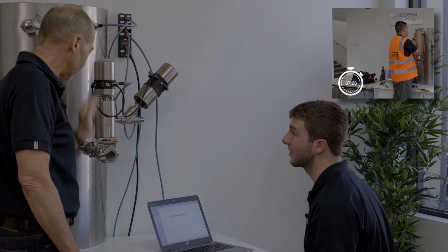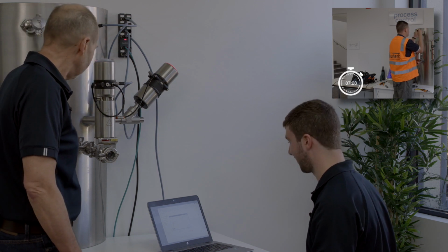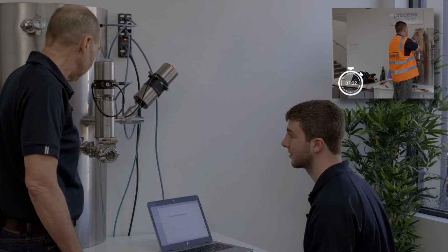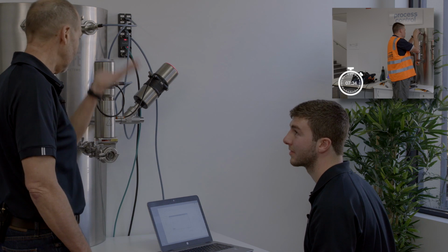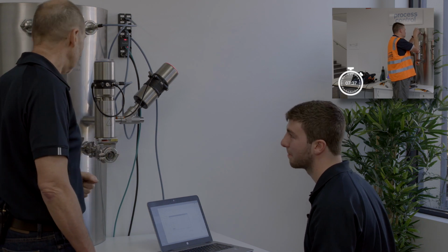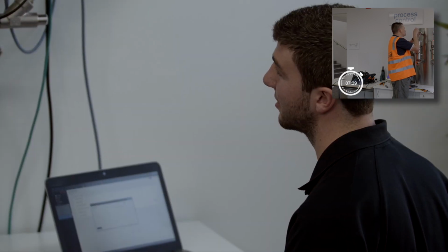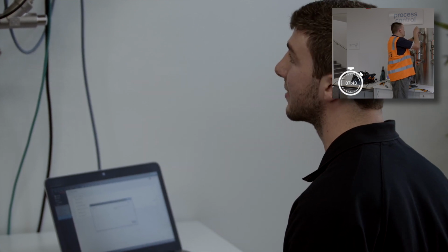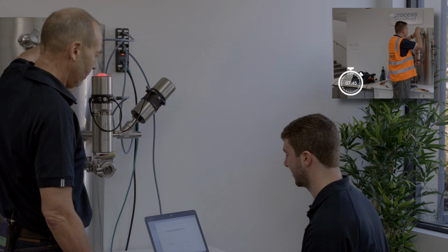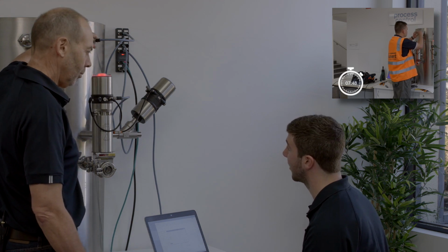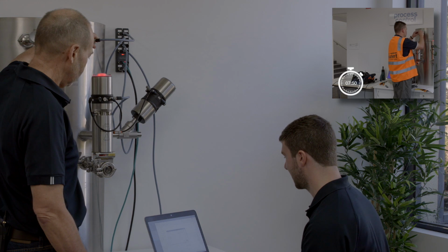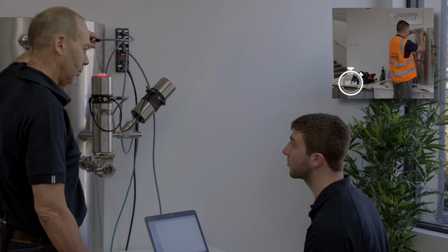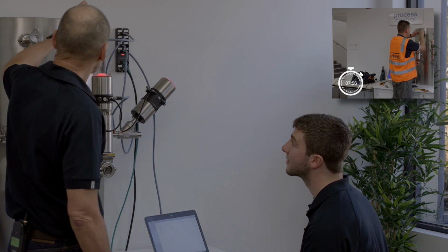Cool, and we can see that valve operating. The valve starts teaching. So the teach function is setting up all of the end positions and the feedbacks, etc. That's correct. So it's teaching that head whereabouts the bottom and top of that valve body are. Can you tell me what the temperature is? Yep, no worries. So we're just waiting for the final teach for this one. And now that that's finished, we can see that our temperature is 23.4 degrees. So 23.4 degrees on the temperature.